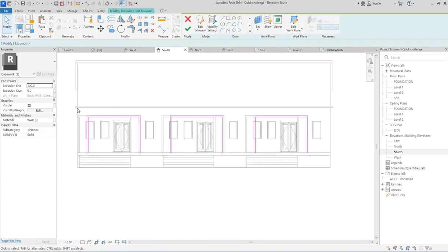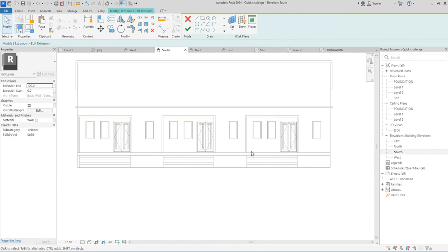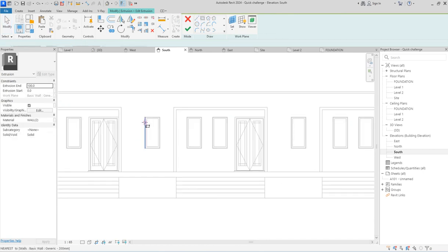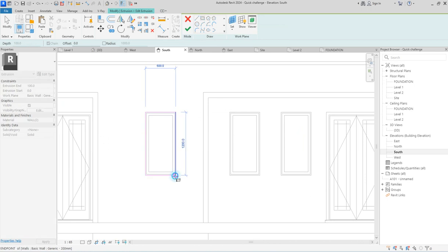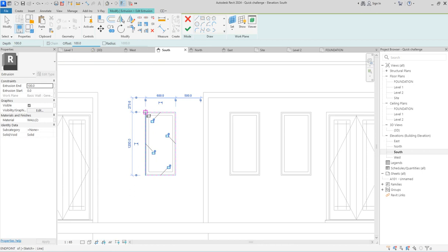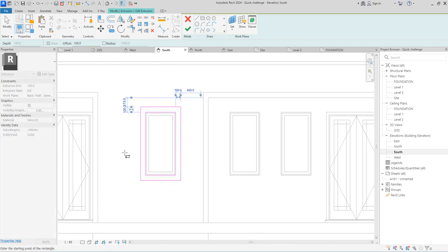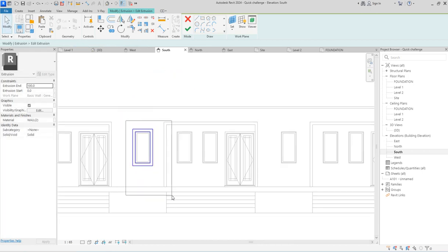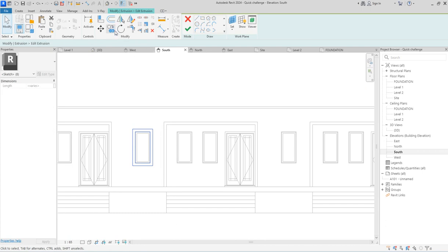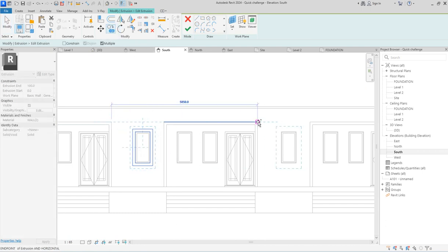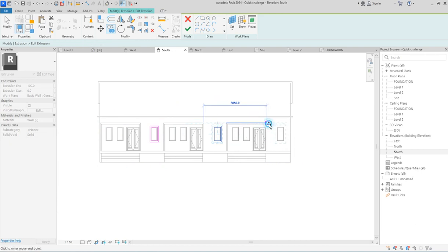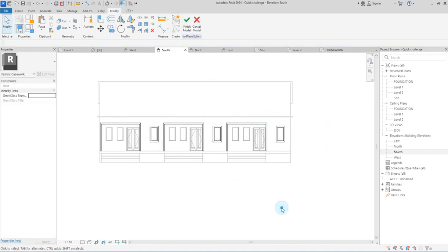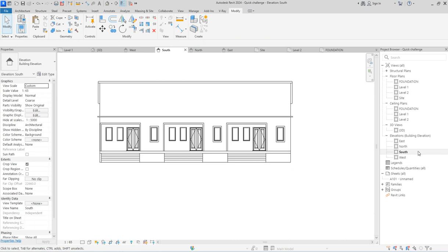So edit the profile, delete all this. Select the only one window at the edge, click. So what next do you need to do? Offset this time around by 100 as well. So click there and then paste the 100 there. You don't do anything that's funny, just what you need to do is to copy and start copying from here, drop it here and drop it here. Finish. Elevations are set. Click finish and see there.